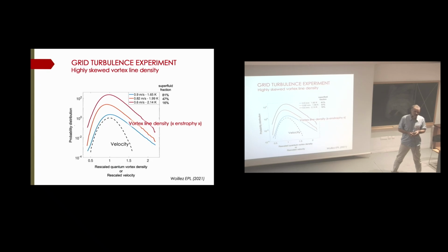Just a small comment. Another physical interpretation of the Taylor scale, even in classical turbulence, is the average travel distance of an eddy over a Kolmogorov turnover time scale. If you ask how much it travels, advected by the RMS velocity, during a Kolmogorov time scale, that's the Taylor scale.